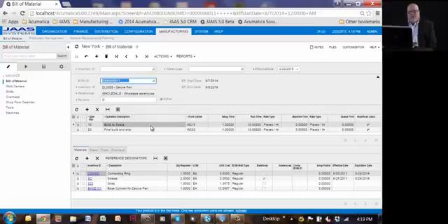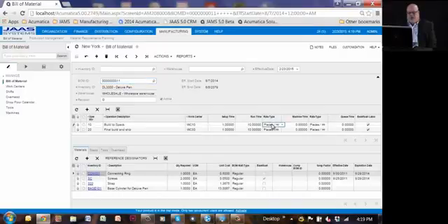We combine our bills of material and routings into one. That way we can time phase our materials coming in through MRP. Within the operation steps, we can set up as many operations as need be, give it an operation description, attach a work center to it. We can track setup time, run time in pieces per hour or hours per piece. Same thing with machine time in pieces per hour, hours per piece. And then we can also apply queue time or wait time.